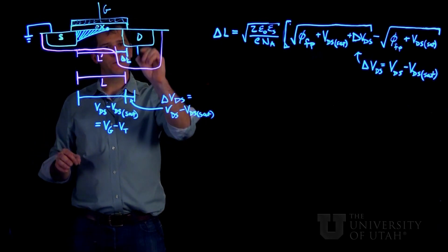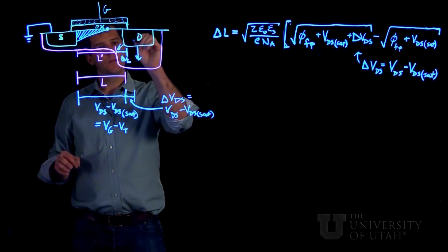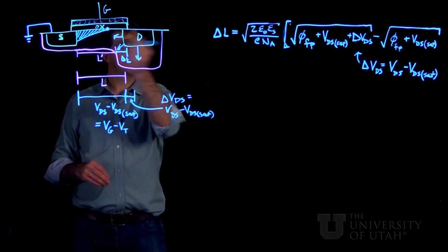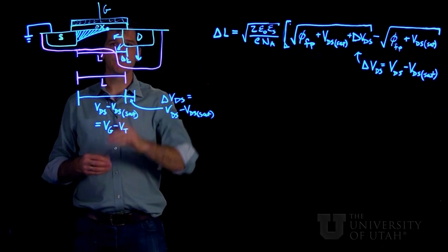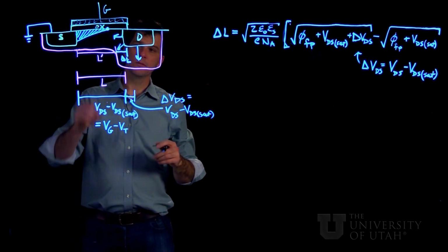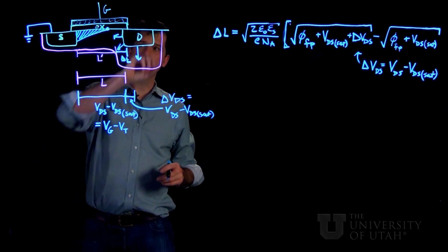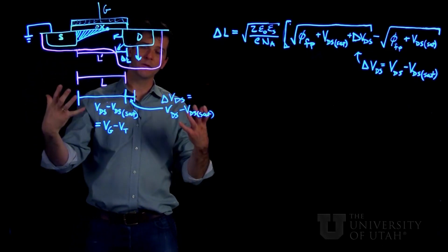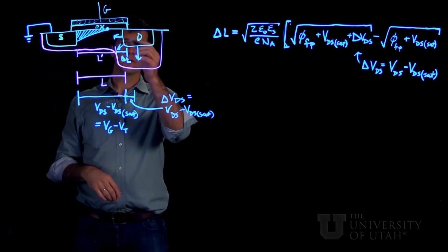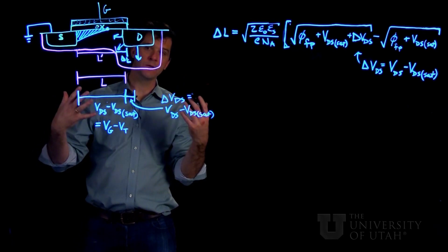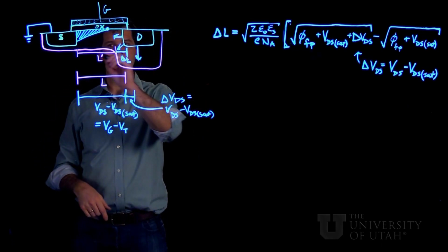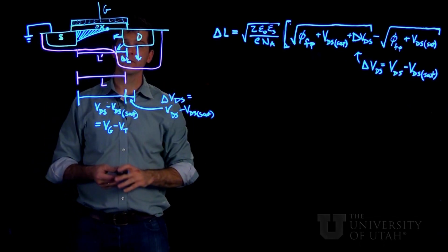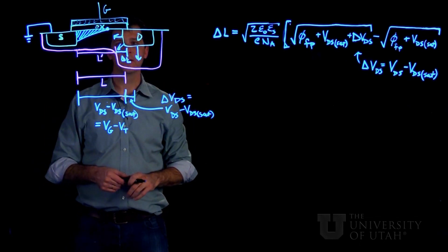So this has brought this depletion width out. But it doesn't just move in the vertical direction, it also has to move horizontally. And so in effect, the depletion widths around the drain and the depletion width that's emanating down from the gate superimpose on each other, and the total voltage, being a scalar quantity, is what determines the depletion width. And really this becomes a three-dimensional problem.